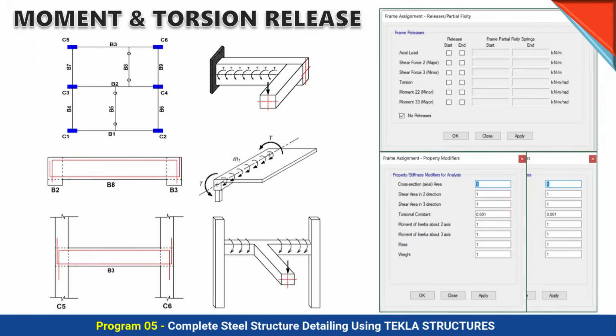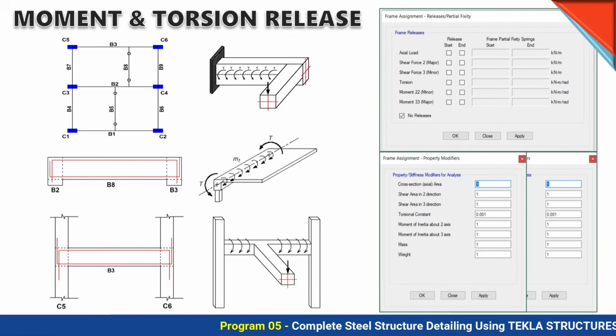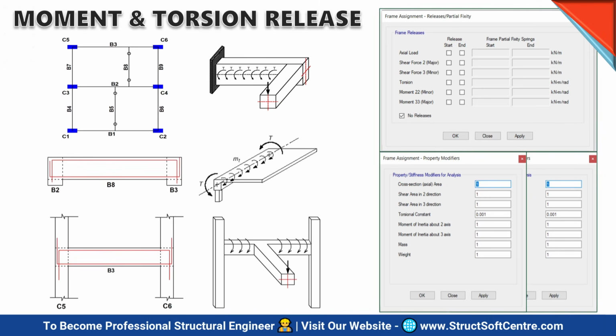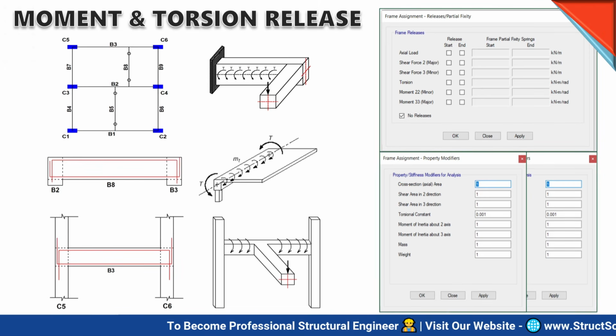And with all of that we are going to complete our modeling part, and after the modeling we have to do some corrections. It might be in your experience that there are different types of beam: primary beam, secondary beam, tertiary beam. So in the Etabs software, how do we make the primary beam, or we can say the simply supported beam, fixed beam, or propped cantilever beam? Etabs does not know this, we have to define it to the software.